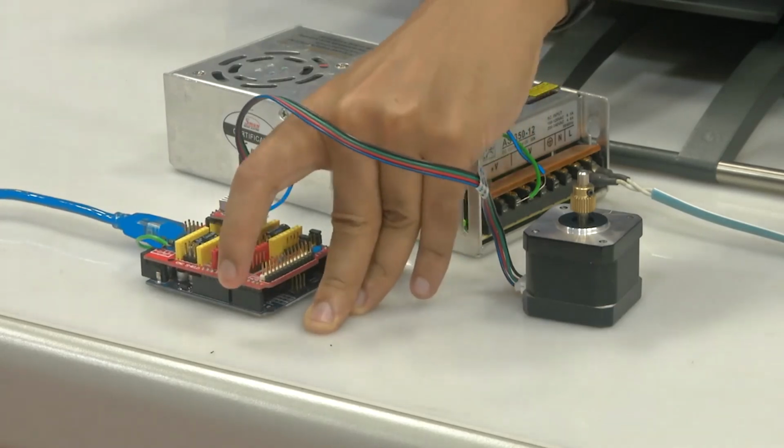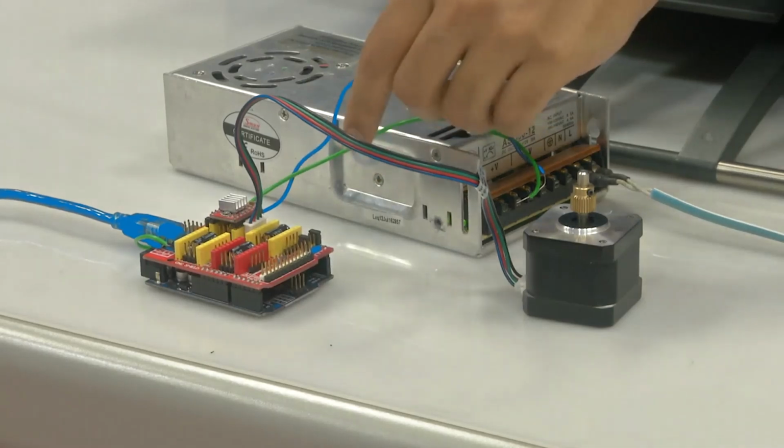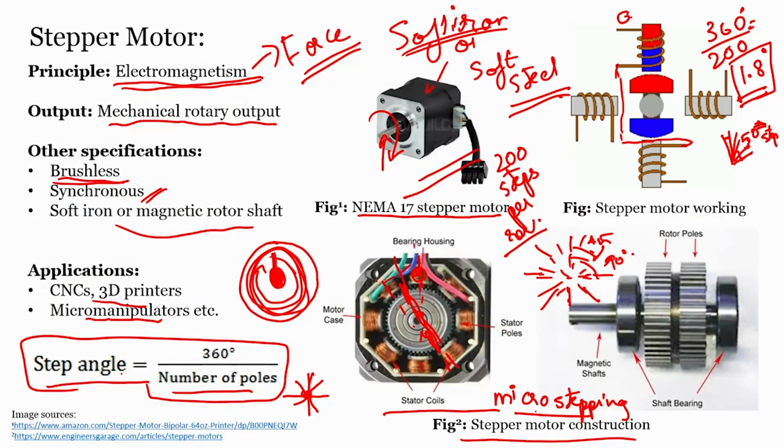Arduino boards are standard, so if we are going to use an Arduino Uno as a CNC machine, we could use a standard Arduino shield which can be easily plugged in, and we can use it for different applications. In this case we are using a CNC shield, a shield made for such an application.